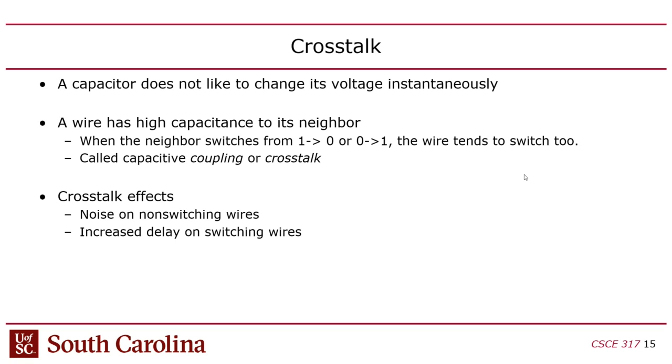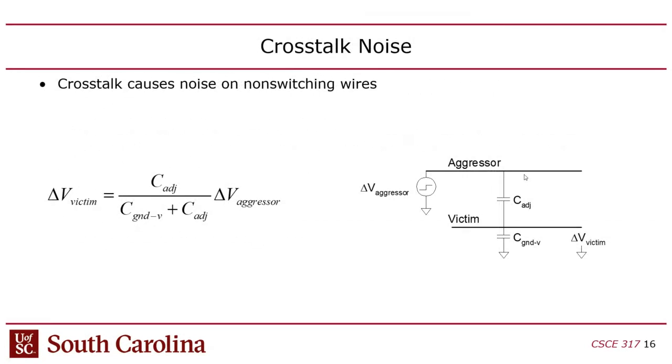So you've got a wire that is supposed to be switching between ground and VDD to send zeros and ones, but it's affected by other wires next to it that make it so it doesn't switch between VDD and ground. It's switching between something, a value above VDD and a value below ground. It also increases delay, because it increases the total capacitance, so it makes the propagation delay slower too. But in this case, we're just worried about crosstalk.